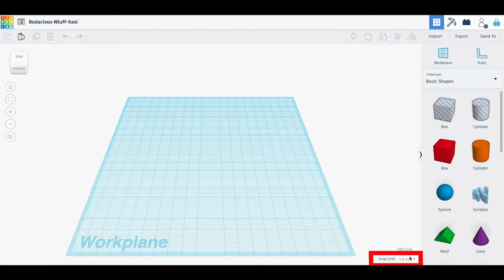Down here you've got snap to the grid. At the moment you've got some options between 5 millimeters, which is quite coarse, and all the way down to 0.1 or off, and we'll use those later for some granular adjustments. And the other tools in the toolbar here are grayed out until we actually drag some objects onto the plane. So let's just look at some of the basic features. Let's drag a box out into the middle of the plane here.